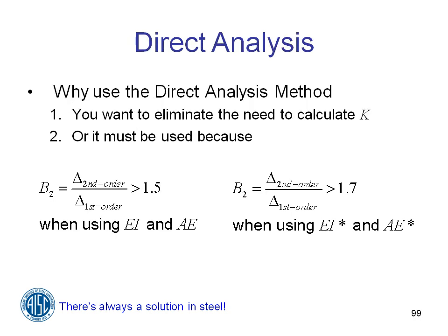So why use the direct analysis method? Why? We've got this method. When we first started presenting the 2005 specification, we talked about it being the method of the future, the way of the future. Why do you want to do it? Well, you want to eliminate the need to calculate K. And why do we want to eliminate the need to calculate K? Because frankly, we really don't know how to do that correctly. The other reason you want to use the direct analysis method is that you have to.